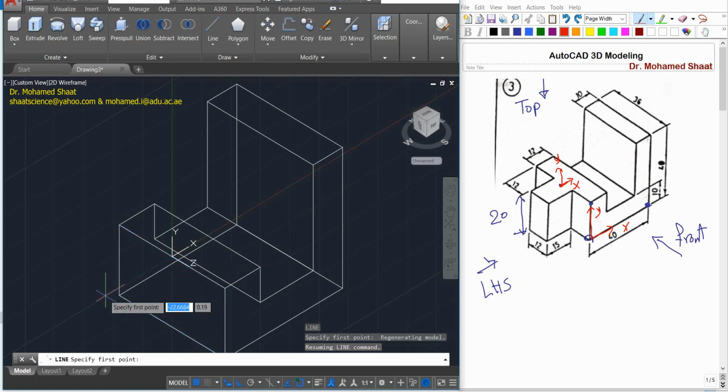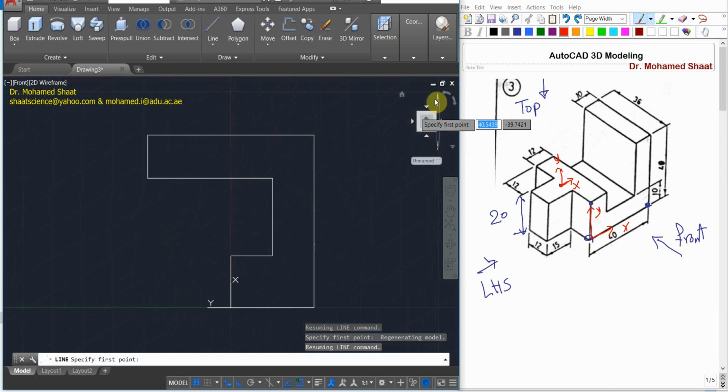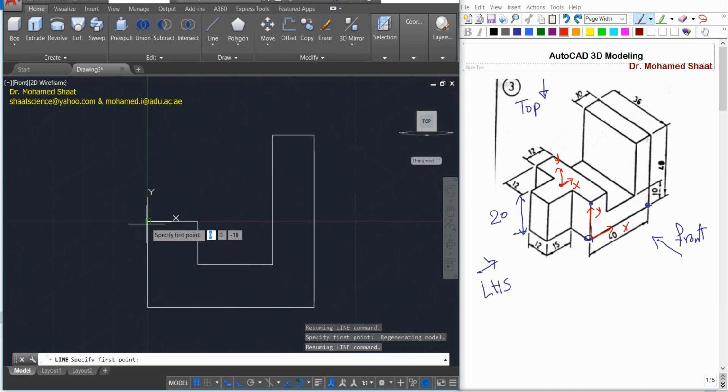So you can start working, you can work in the 3-dimensional representation, or even return back again to the top view and give it rotation. And I won't click on this point, and instead I'm just gonna move, because I need a point here at a distance of 15, kind of, right? So one of the things, yeah, because as you can see, AutoCAD gives me end points.